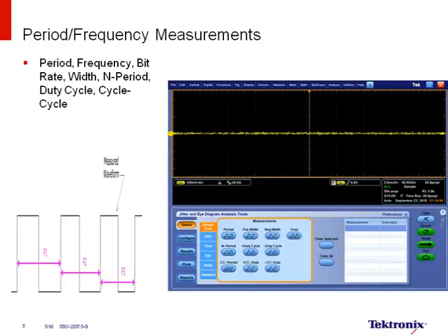For example, most customers expect to see a peak-to-peak measurement. However, a statistic that's perhaps more important than peak-to-peak is standard deviation. The root cause for this is that peak-to-peak will grow with time, and the standard deviation number converges very quickly.